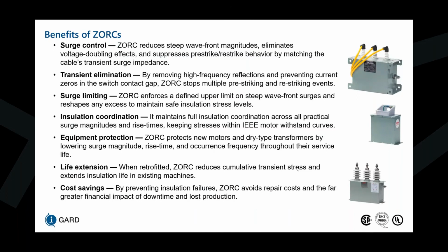Surge limiting, so ZORC enforces a defined upper limit on steep wavefront surges and reshapes any excess to maintain safe insulation stress levels. And that's where insulation coordination comes in. So it maintains full insulation coordination across all practical surge magnitudes and rise times, keeping stresses within IEEE motor withstand curves. In terms of equipment protection, ZORC protects new motors and dry-type transformers by lowering surge magnitude, rise time, and occurrence frequency throughout their service life.